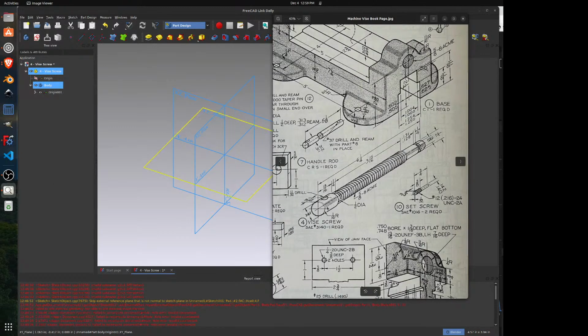I could actually see doing this as, let's say, 1, 2, 3, 4, 5. You could technically do this with probably 6 extrudes. You just extrude this 3/4 inch diameter, then extrude the little relief here for the threads, then extrude the diameter for the threads, then extrude this smaller diameter out here, then extrude the relief out here, and then extrude the final bit.